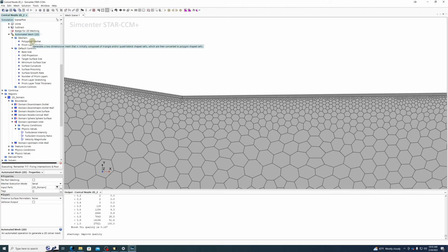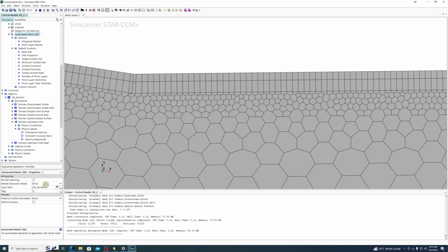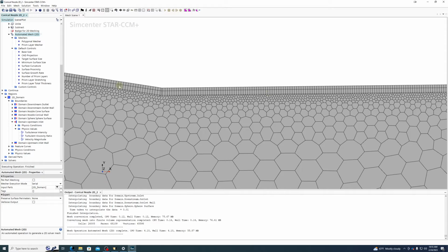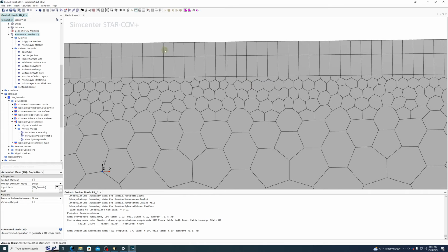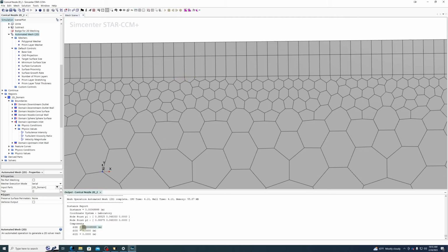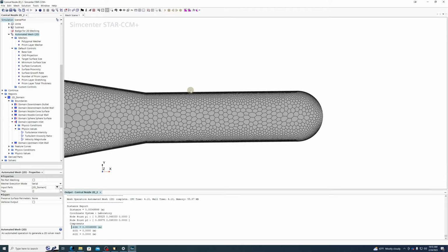So at this point, they're probably not going to get any smaller. Oh, actually, they got smaller still. Okay, let me keep on cranking this up until we run into the minimum cell size. So theoretically, at some point, these will stop getting any smaller. Oh, yep, there we go. You see, these didn't change. These changed a little bit because we're at this point where these cells are already 0.5 millimeter in size. So let's check that. Oh, yep, look at that. That is 1/2 millimeter in size. So these cells are already as small as they can get, and they won't get any smaller because of our minimum cell size.